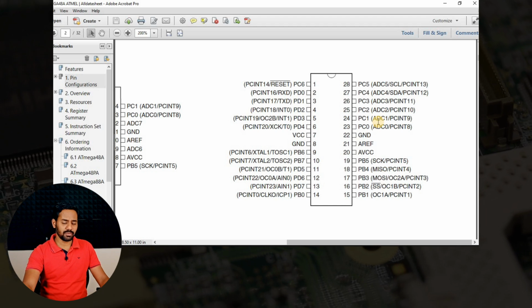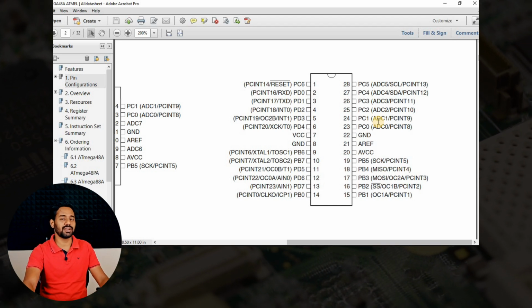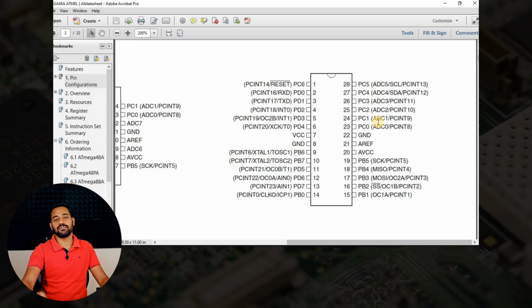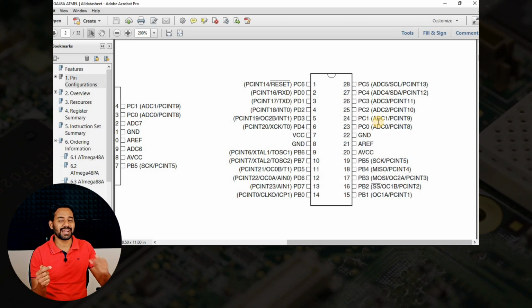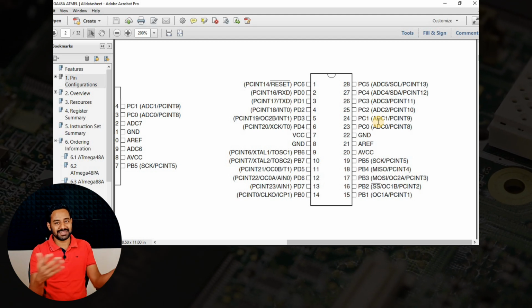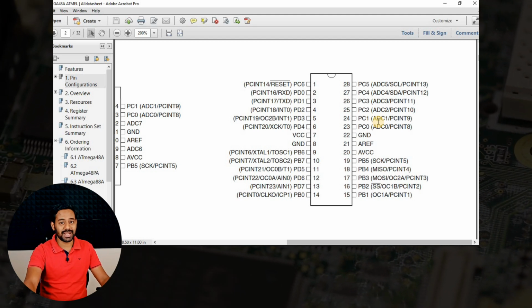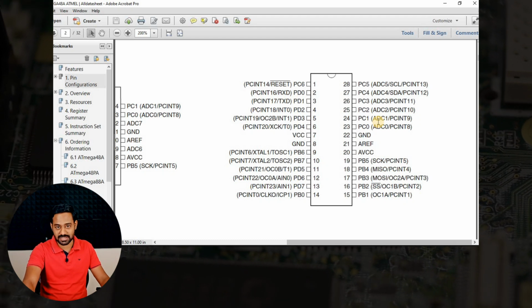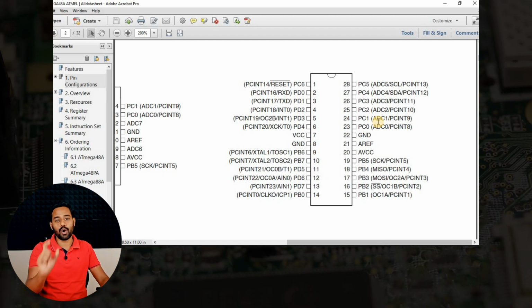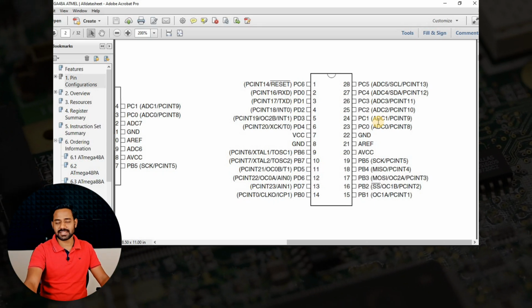It is going to be a little time consuming and very focused work, so make sure that you do it carefully, because if you miss any particular pin number and pin name association and mix them up a little bit, then the entire schematic library is going to be a waste of time. So make sure that you spend good focused time on developing such complex schematic symbols when you're doing a library activity. So let's get started with that.